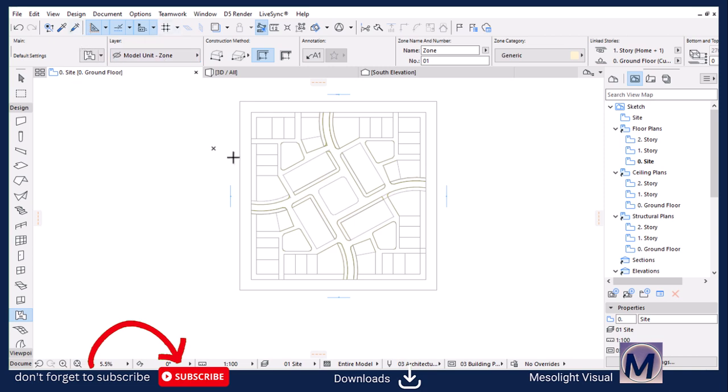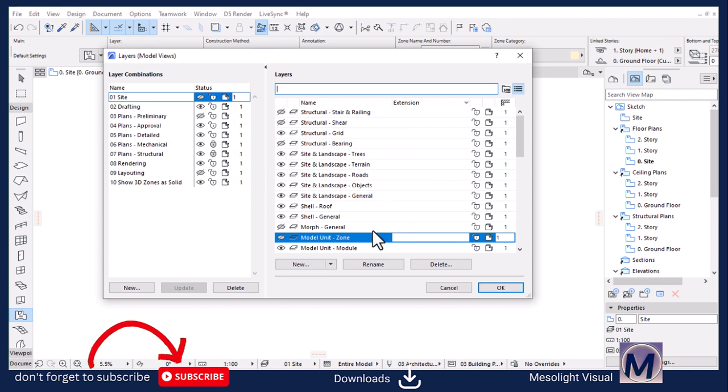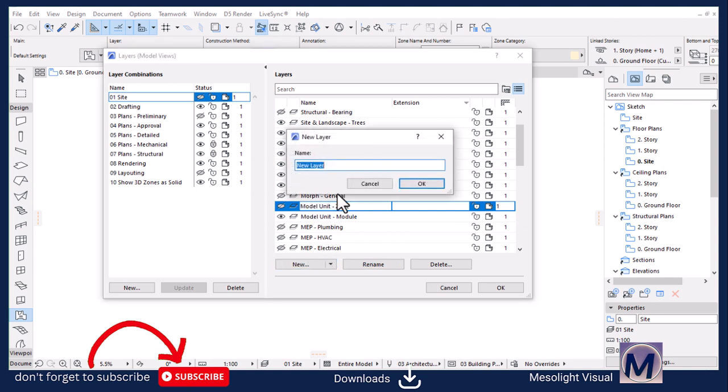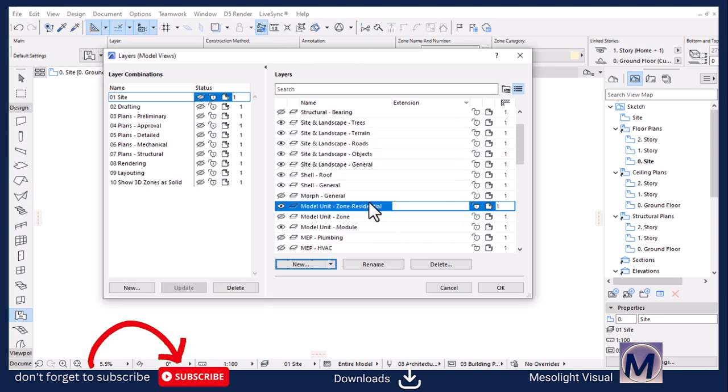So what I'll do, I'll press Control L to open the layer settings, and then under model unit zones, let's rename it in order to access the name, and copy, hit on new, and then paste it there. The reason why I'm doing this is because I want to respect the layer system of ArchiCAD, and whatever I'm creating has to be on the subcategory of that. So for this case, it's going to be zone. This one is going to be residential. Hit OK. Make sure it's updated on the site layer condition, and then let's create another one.